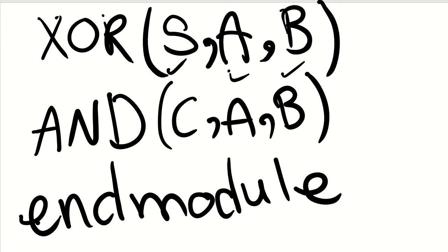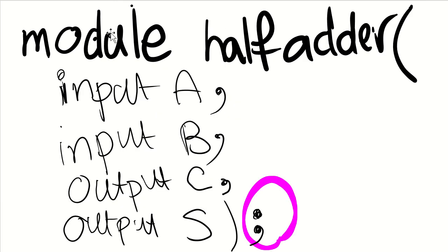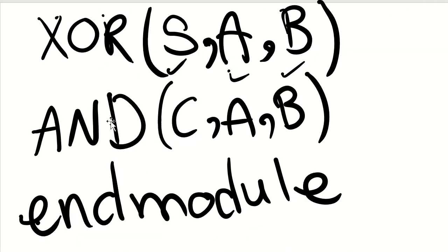Okay, so this is just to expose you to Verilog. Now again, first you have to create a module. Then it comes with a name. Put your inputs and outputs, and go see what are the basic modules in your circuit. And these keywords are already known to Verilog. So you type this, and once you're done, you have to finish it up with end module.